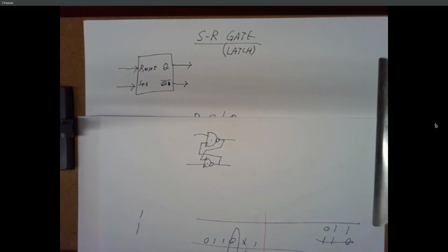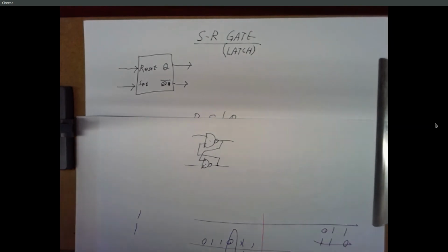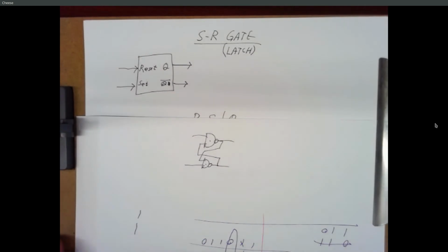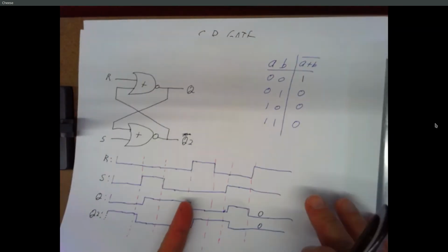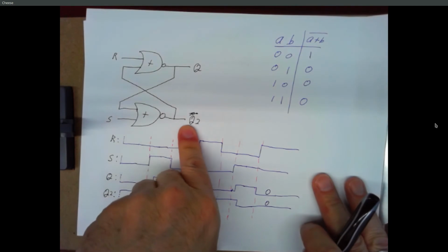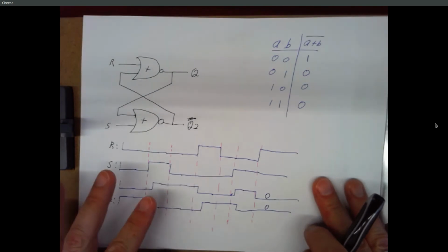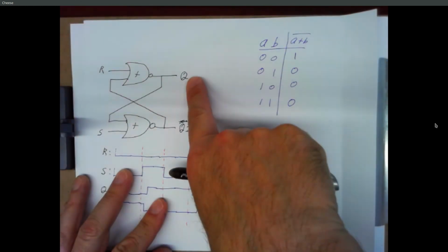So if the outputs are forbidden, what would actually happen? Sorry, say that again? If the outputs were forbidden, you know, they say it's both R and S or both 1, then what would actually happen to the circuit? Like, you just say that it's kind of impossible, but what if you put an LED, will it keep on flashing? So the way this is wired, if R and S are both 1, both outputs just go to a 0. Straight 0? Yeah. So it's nothing really weird. It's just slightly strange that this is not the opposite of that, because usually it is.